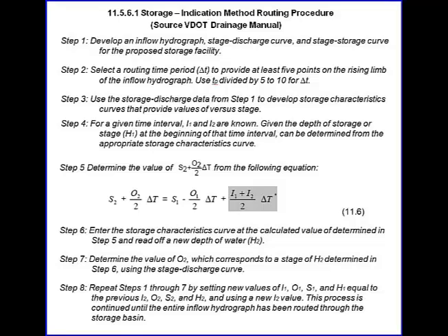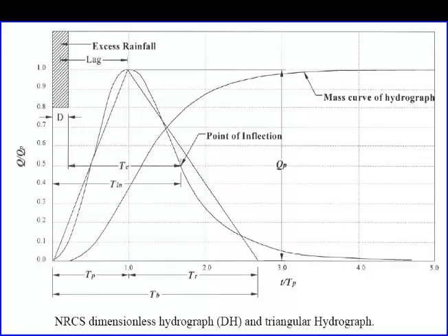In order to determine the adequacy of the ED pond to hold the water quality volume, and to safely convey the 10-year and 100-year design storms, it is necessary to route the inflow hydrographs across the pond, with due consideration to pond storage and the outflow rates. This is done using the storage indication method routing procedure as given in section 11561 of the Drainage Manual. For the inflow hydrograph, the program uses the NRCS dimensionless unit hydrograph.